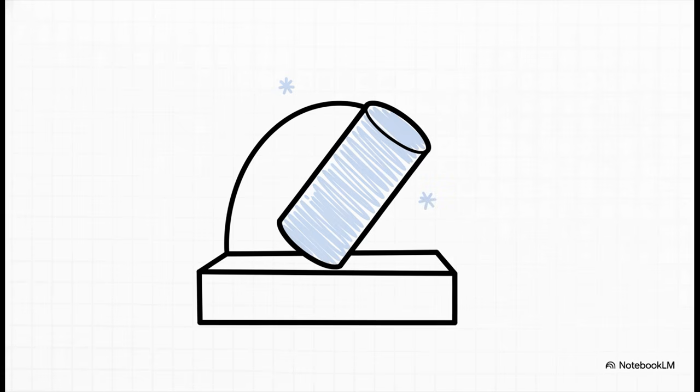The really crucial point to remember is this. If the blueprint calls for a 47-degree tilt or a 15-degree taper or a 72-degree angle, angularity is the required symbol. And notice that we call it a basic angle. In GD&T, a basic dimension is a theoretically exact value. You'll usually see it enclosed in a little rectangular box right there on the drawing. The angularity tolerance zone is then built perfectly and evenly around that theoretically perfect 47-degree basic angle.